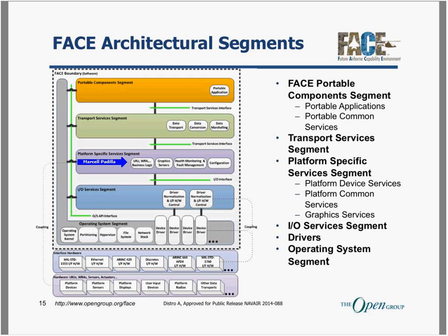This allows this service to take the information it receives from the I/O service, that was received from the bus that received it from the sensor, and cast that into data that the rest of the software in the system can understand in a standardized fashion. This also allows the ability to control some basic controls of that sensor or effector.